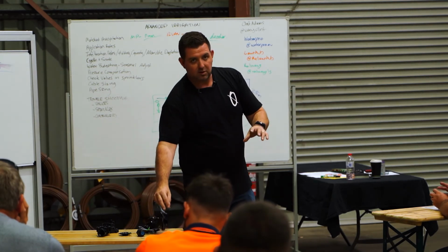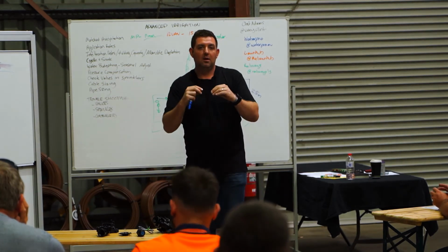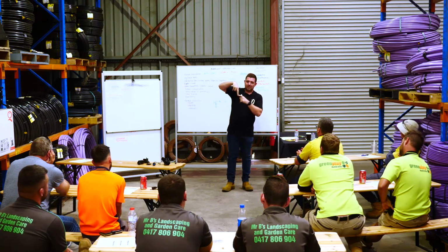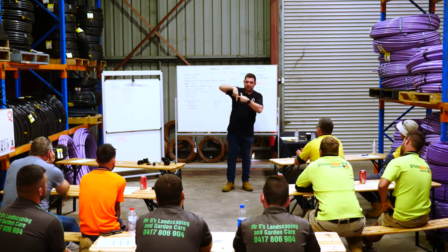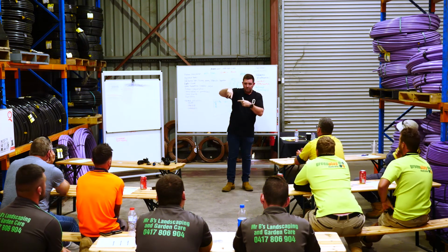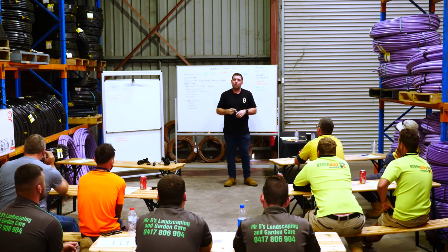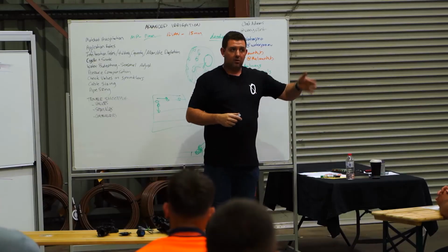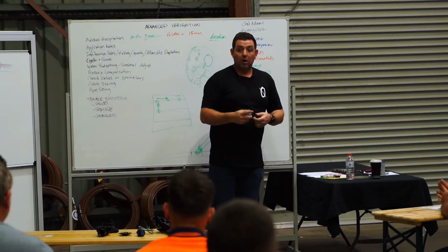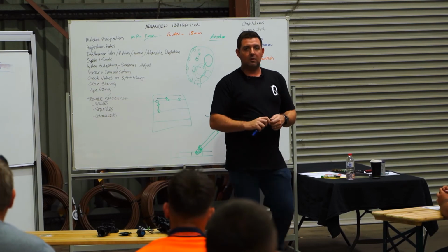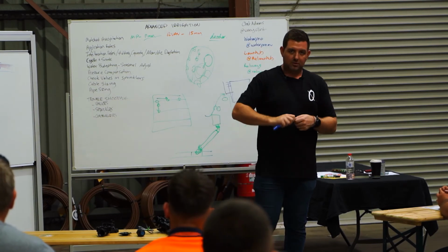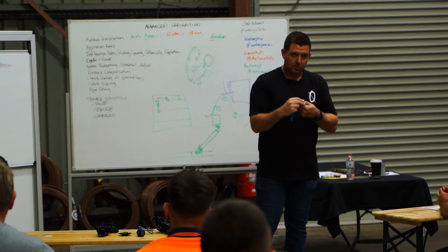Those wire joiners are designed to be able to just stick the wire in and crush, and it actually has like a blade that goes down around the cable and pierces into the plastic and touches the metal. With the really small wires, it doesn't always do that. So if you're finding that you're not getting it to work, if I was doing it with those wire joiners, I'd actually sheath the cable back, twist them together, stick them into the wire joiner and crush it.